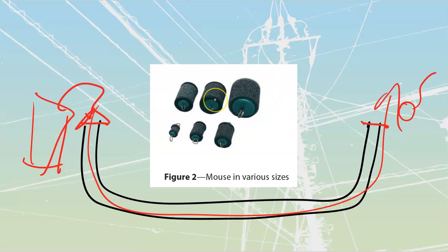These are the mice. You can buy commercial ones. You can make your own as well. They're really easy to make. Sometimes what we will do is pull these things in. Note how they've got a string line on either side of these things, so you can put them in ahead as well. Sometimes we will actually put them on to clean a conduit out, to size it.